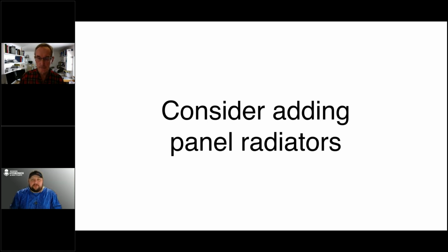We did have one other question about outdoor reset controls. It's kind of a wide open question, and we could probably spend an hour just talking about outdoor reset controls. But real quick, you got any tips or considerations on outdoor reset? Well, I definitely like outdoor reset because it doesn't force the heat pump to operate at water temperatures any higher than necessary. So anytime we can bring that water temperature down and still adequately heat the building, and that's the whole basis of outdoor reset, we're going to improve the efficiency of the heat pump.